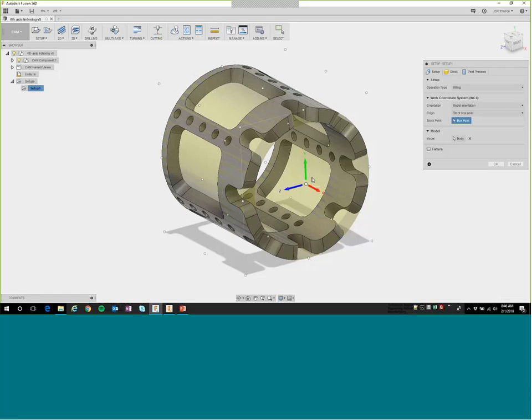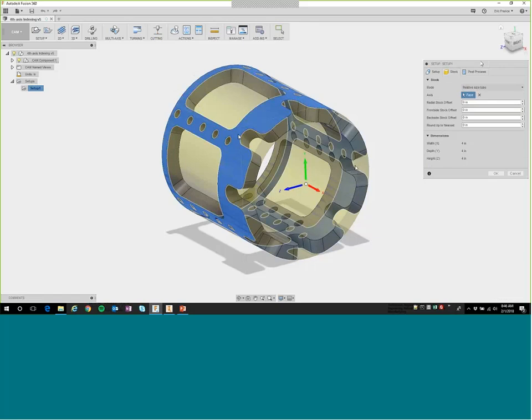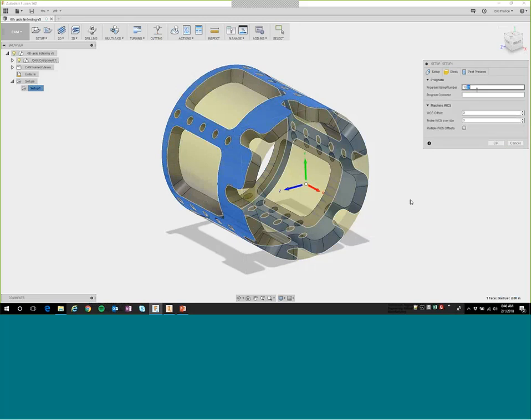We've identified where Z is. The stock for this is just a relative size tube. We've got no offsets. We've got pretty good consistency from the supplier with regard to providing a 4-inch OD on the tube itself. So we're pretty happy and able to leverage that without worrying about it too much.